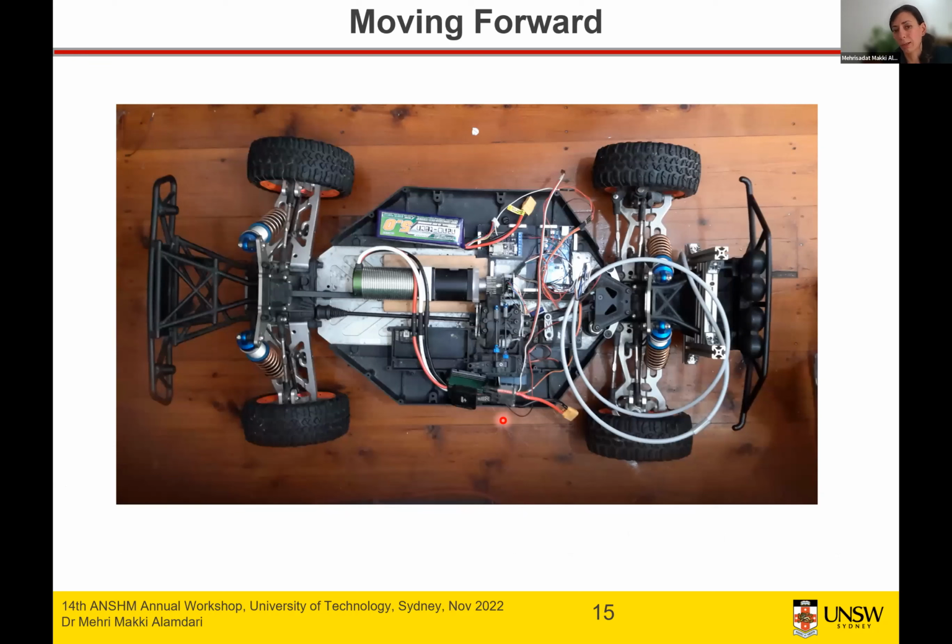And the good thing about this car is that we have the capability to change any dynamic characteristics of this vehicle: the suspension, the mass, axle distance. Because it's fully autonomous, we have control to keep its speed fully constant, which is another challenge in the context of drive-by bridge inspection. And each time we can calibrate it using modal analysis.